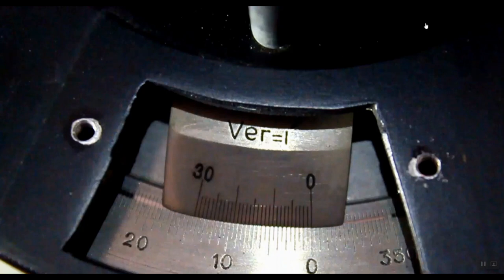There are two verniers and this represents one vernier. And it has two scales. One scale is the main scale. This represents the main scale. And the other one is the vernier scale. The main scale can be used to measure angle or readings from 0 to 360 degree. The vernier scale is used to attain accuracy and it consists of 30 divisions.